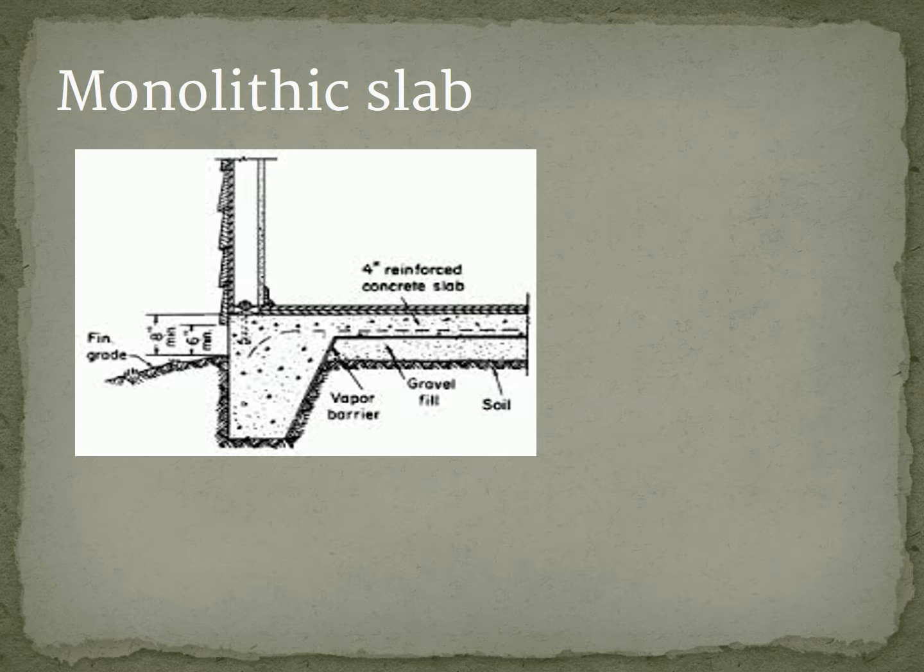On the monolithic slab, as you can see, this is going to be a 1-pour slab. So you can see as we look here on the outside of the slab itself, it's going to be really wide, especially as you go from the bottom up to the top and up to where the slab itself will start to come across the house. You can see this is a really wide poured slab. This is going to be much different than your other 2 because there's no way you're going to angle drill this from the outside. So in a lot of ways, this is going to be a pretty simple termite treatment because you're going to drill your outside patios, your outside porches vertically straight down, and then you're going to treat your trenches, but there's going to be no angle drilling into this slab or underneath the slab.